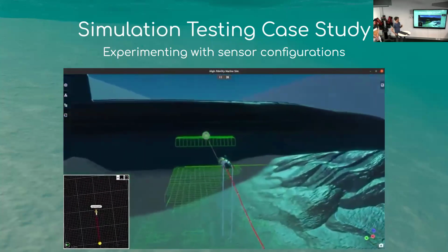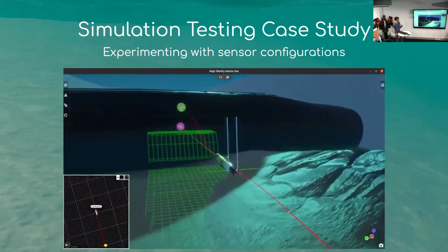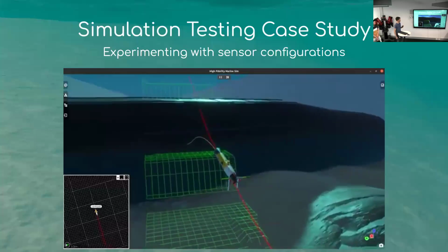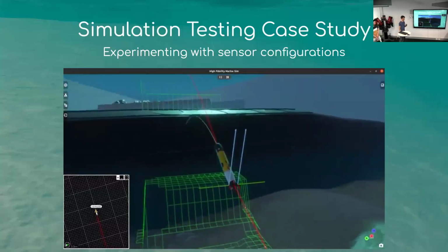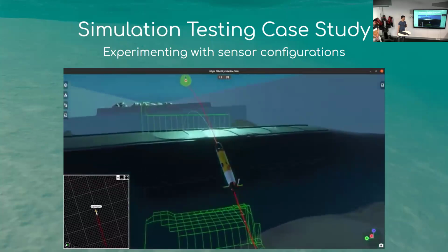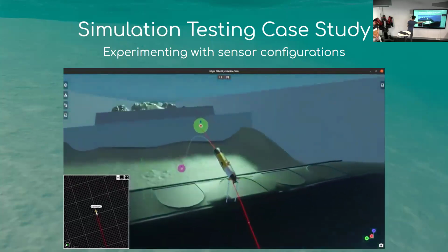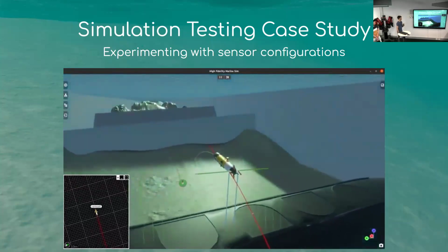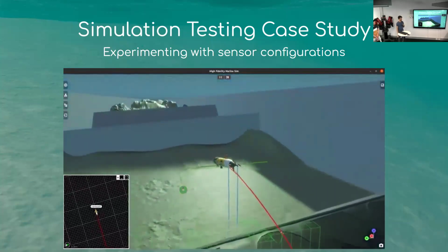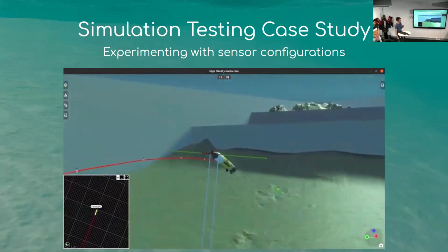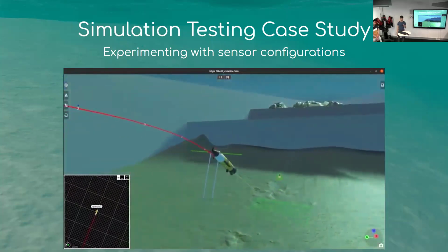And you could get better. I also did a few tests with different kinds of arrangement of sonar, one in particular being a multi-beam on the front, even if it was just a narrow plane. And you could get better results in terms of the accuracy of the grid. You can see this grid gets quite high at the front, but eventually gets drawn down by the DVL's beams. But just this one cheap sensor was going to be sufficient.